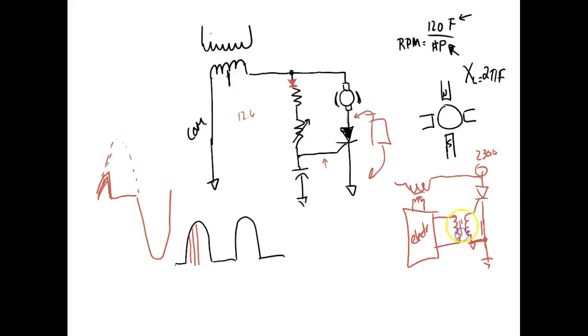And then this will be this little pulse transformer. They put those little dots on there so you know how to hook it up. Because if you have 2 leads on the output and you hook it up backwards, you'd be getting your positive pulse when the SCR was reverse biased. So these are pulse type transformers, and what they allow us to do is have a low voltage firing circuit control a high voltage circuit. These are isolation transformers.